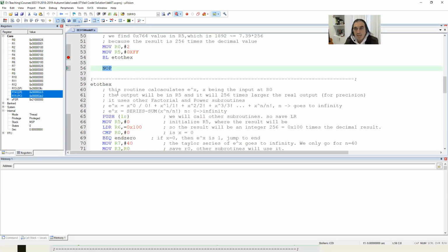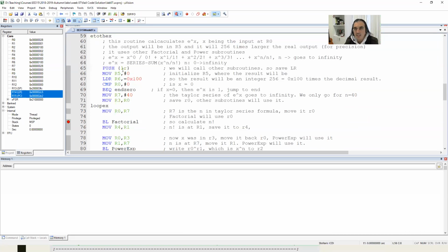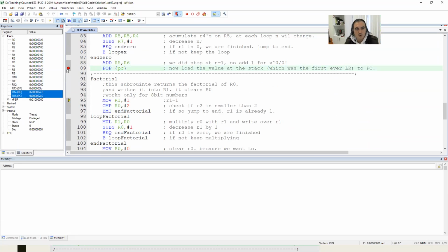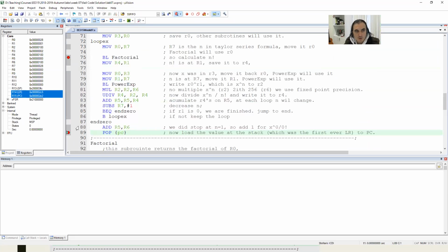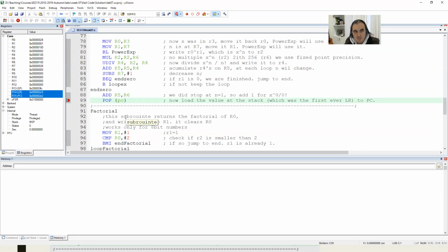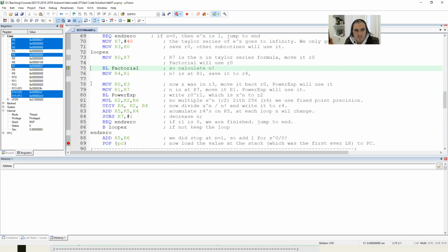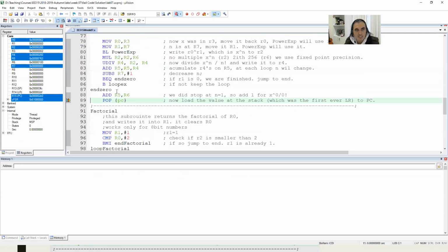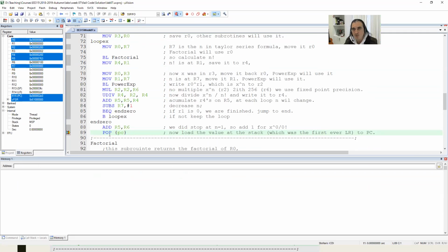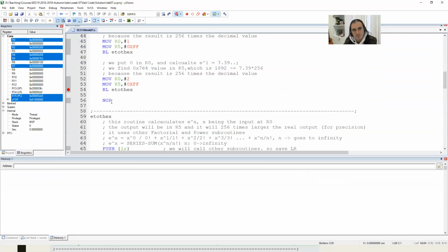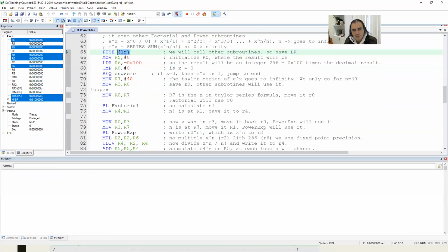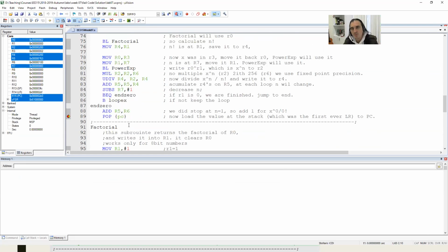Where is it? Actually, we have saved it in the stack. So if you go to the end of this code, I'll put a breakpoint here. I'll press F5 and jump directly to PC there. So it's going to be stopping there. So guys, I'm going to get the value inside the stack because I haven't used the stack. And there is only one value at the stack, which should be my return way back home because I've pushed that value. I'll be writing it to the PC.